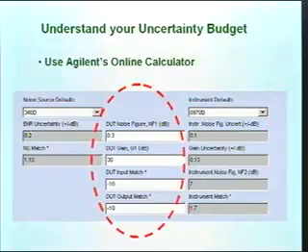And then you type in the numbers you've just measured for the noise figure, and I'm standardizing here on 0.3 and 30 dB. And here, these are numbers that you can measure or guess at or hope for. And so we'll look at something with a reasonable input match.